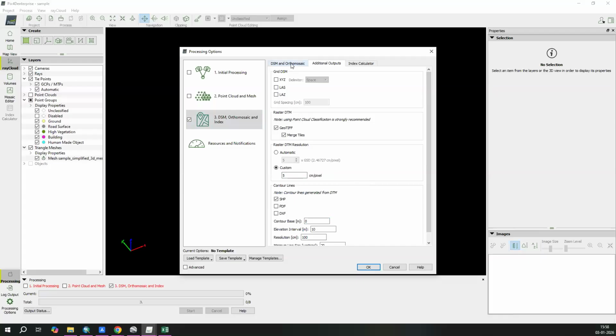That is how your error value is calculated. For example, if you have a horizontal error of 1 centimeter, your vertical error will be 3 to 5 centimeter. That is the maximum permissible limit. When the error is more than 3 or 5 centimeter, your data is wrong. Your data should not go beyond the 1:3 and 1:5 error proportion.